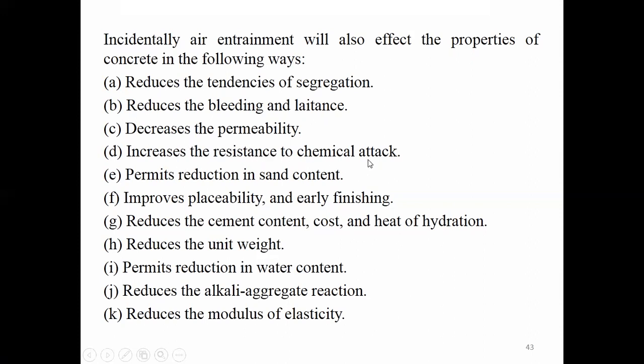It is also resistant to chemical attack. I told you previously, in the strength point itself, that it will reduce the sand content. So it will reduce the filler material content, but it will increase the cement content to some amount. It also depends on the mixing procedure. It reduces the unit weight of the concrete. Water content will get reduced.